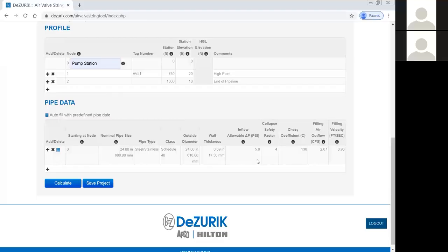don't do 5, do 3. Plastic pipe's more fragile, so it uses 3 PSI. And so if I would have chosen PVC, that number would have said 3 instead of 5. AWWA also recommends a safety factor of 4. So even if it just calculated the strength of the pipe, which is a ratio of the diameter and the wall thickness and some other stuff thrown in there, it still says put a safety factor of 4 on there.